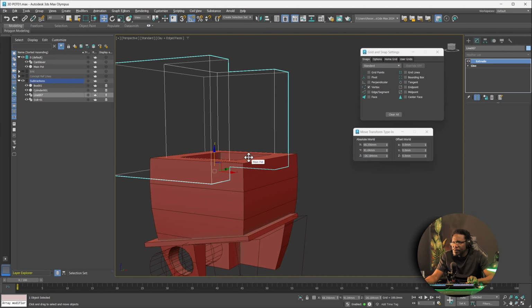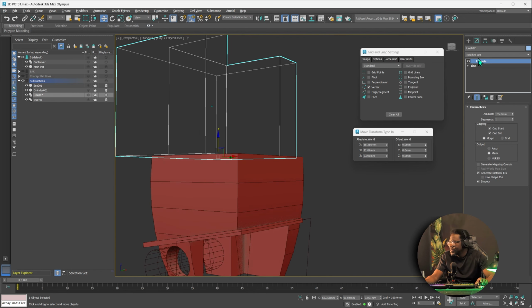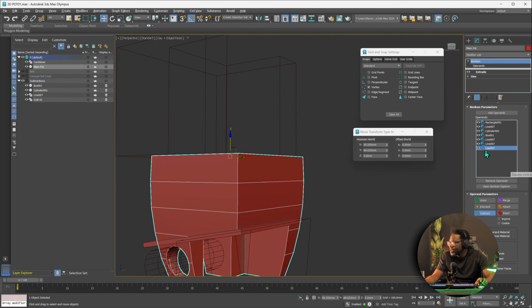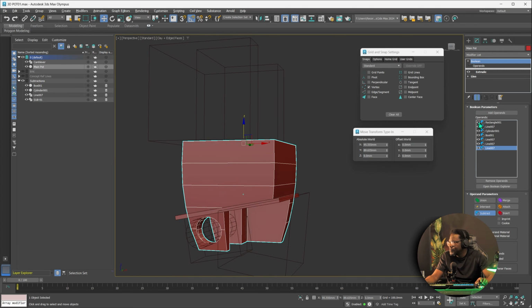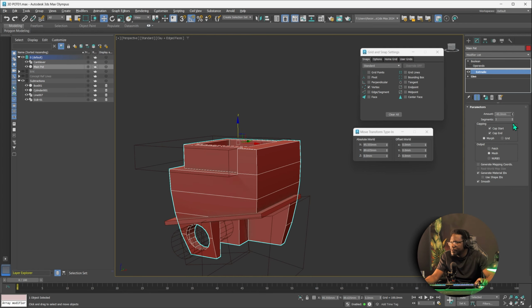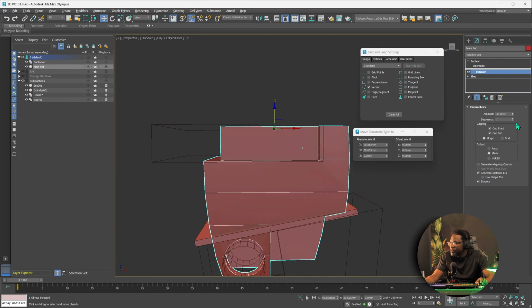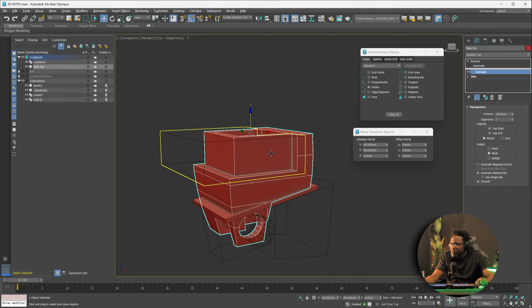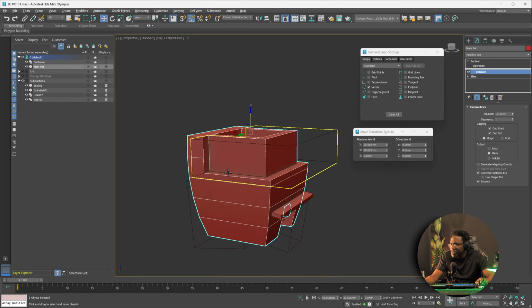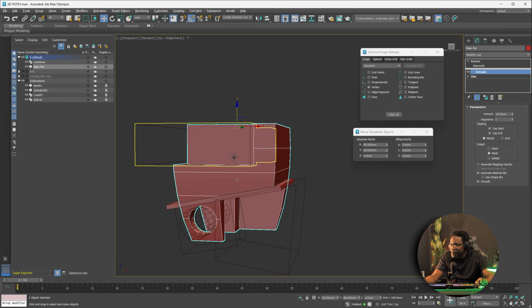That was a problem. If you remember, we can't physically move it. So let's go back here. It was already added, but we can't move it. So we have to use the parameters to move, not the transform. So this will give us that inner edge that we wanted to achieve here, right?